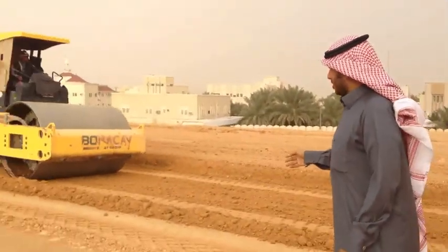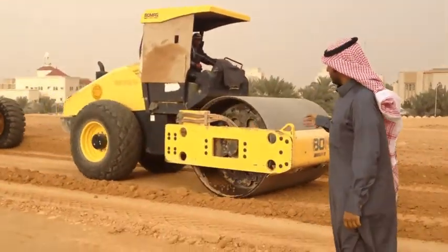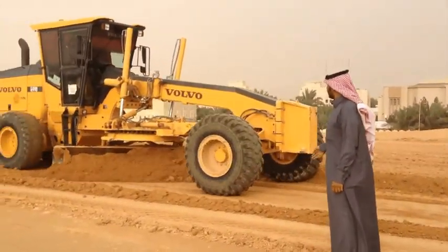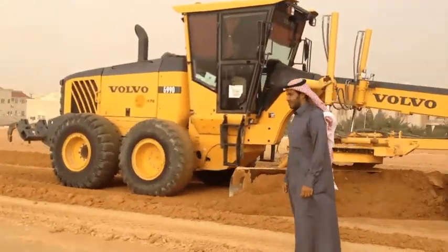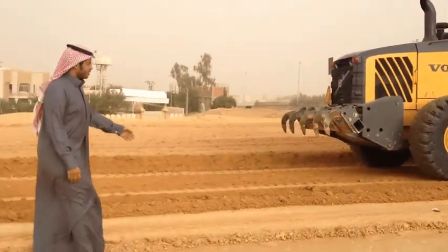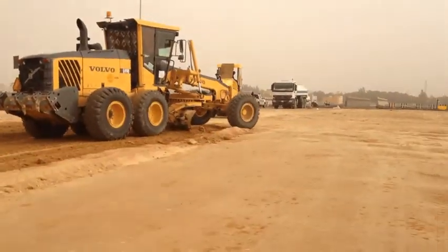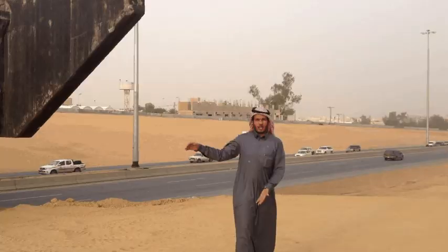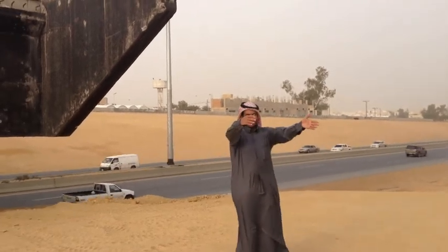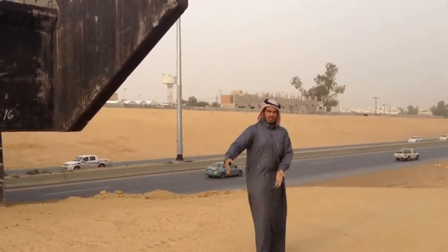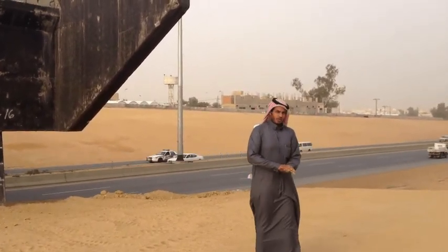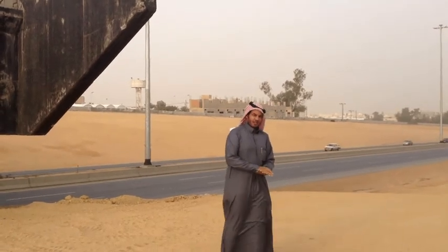It's first dumped into place by large dump trucks and then graded over using machines. Once the rock fill has been applied, it's typically compressed down into the ground by using a steam roller or by driving over it with heavy construction machinery. This helps establish the solid rock-packed area as a durable surface capable of withstanding the large amounts of weight associated with vehicles of all kinds.